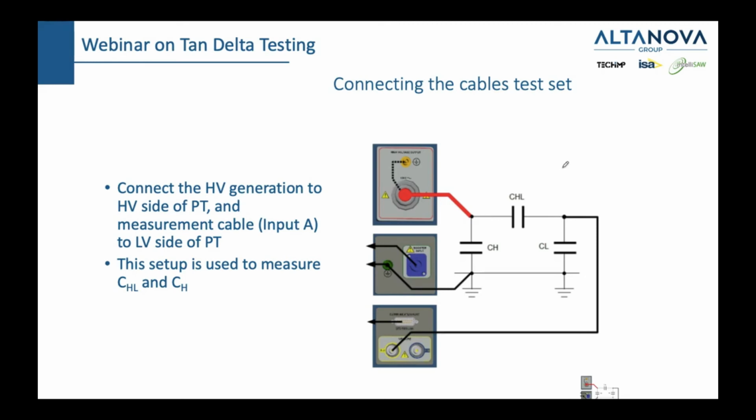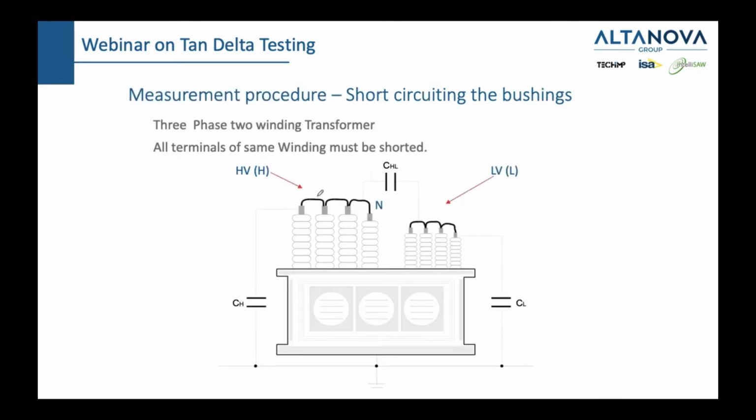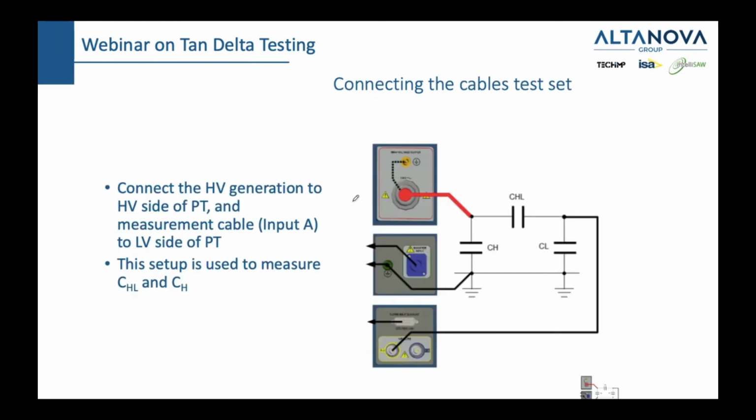We didn't short-circuit primary together with secondary; we short-circuited primary and secondary separately. The neutral is also taken into consideration when we did the short circuit. You can do this with a thin wire because the current flowing will be milliamps, so you don't need thick wires. Of course you can, but it's not necessary.